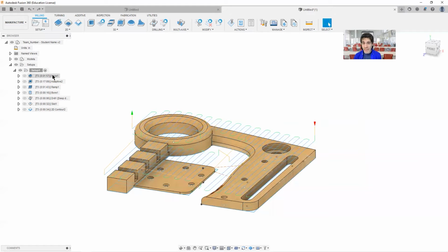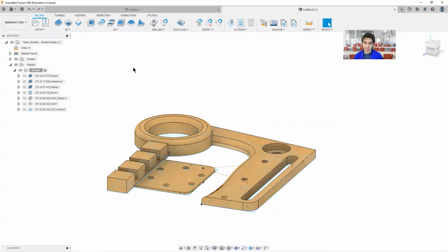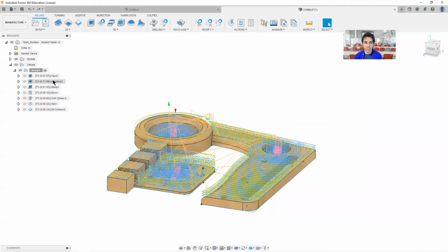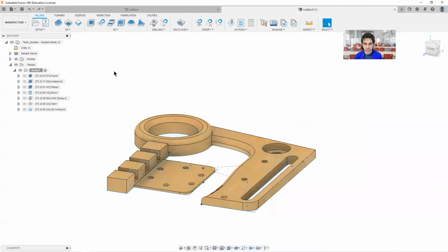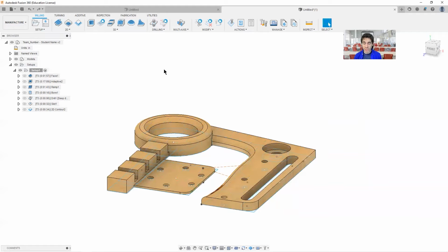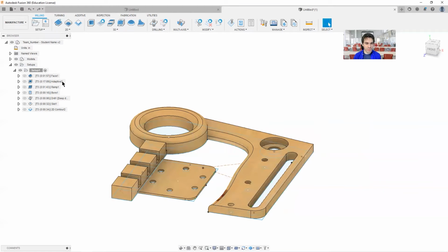In truth, many parts can be done in a single 2D contour cutout operation, or your part might only need a single boring operation and then a 2D contour to cut it out. Or maybe you only need an adaptive or a pocketing operation. You should do some experimentation to see what the most efficient or practical toolpath is for your particular part, which is going to have its own features.